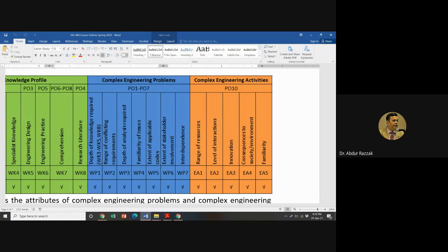For example, you have a simulation software. You are simulating a very complex circuit, or your project. Then you see that in some stages you are not getting any output. Then what will you do? For example, in the 4th stage you are not getting output. Then go to the 3rd stage. Is there any output in the 3rd stage? You see that there is no output. Go to the 2nd stage.